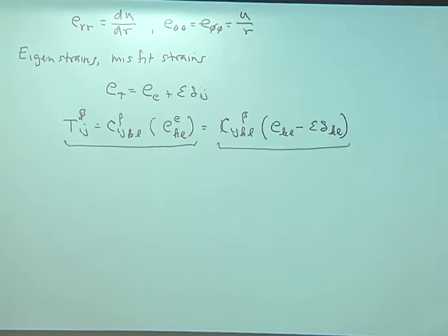So this is the total strain, remember? It has to be compatible. And that's the eigenstrain. And so you see you have this minus sign there, right? And that's because we're using the alpha phase as the reference state for strain. Basically, we're measuring that relaxation, the elastic strain, relative to the alpha phase.